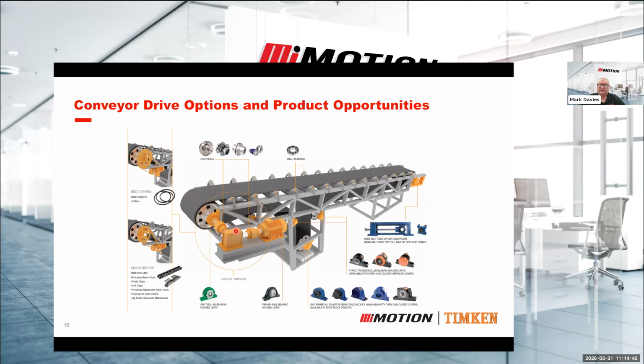So normally, if it's an elevated conveyor, as this one is, so it's lower at the bottom, higher at the top at the head end, the drive is always at that head end, so it's pulling the product up the hill, not trying to push it.